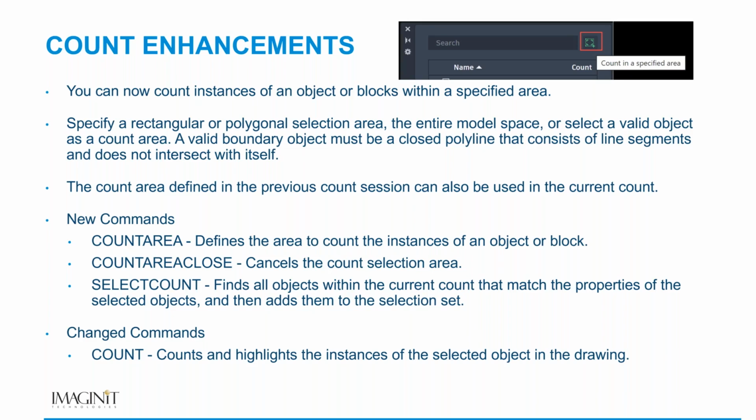What is the latest AutoCAD version you can save a file? This is still the 2018 DWG format. I can change any of these files and I can still open them in 2018 without having any problems. Is there a way to tell if the drawing contains a trace without having to open the trace window? Generally speaking, if I open up a drawing that has a trace in it, it will usually prompt me that there's a trace in this drawing. It will ask me if I want to open that.